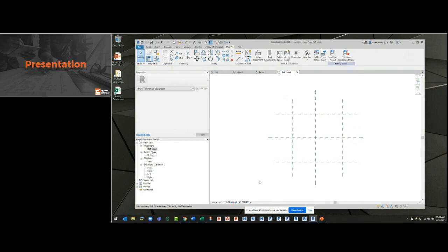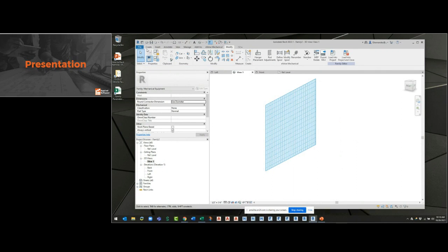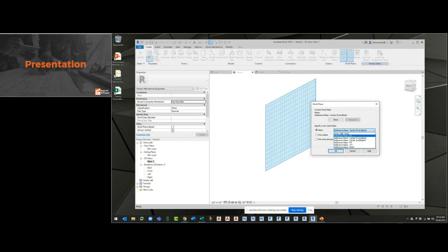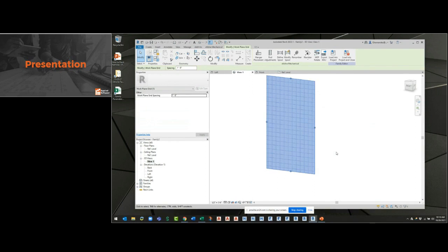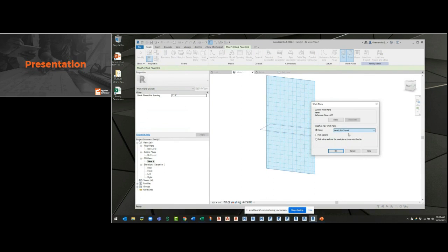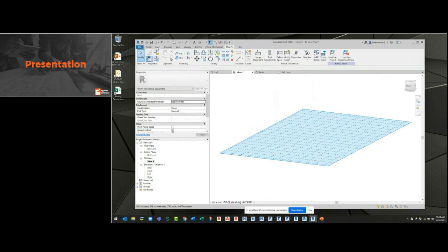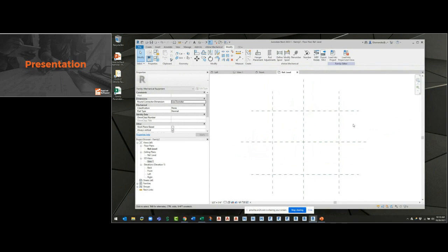Again, it's important to label them so that when I'm over here in my 3D view, or I'm trying to build off of something, and I go to set the work plane again, I can go to these new work planes, or reference planes, that we just created. So if I want to go to the left, it's now left. Let me set this back to set reference plane. Set this base first. So you've got to make sure you know what you're drawing first. Okay, so I'll go back here.